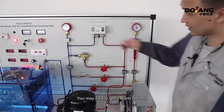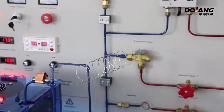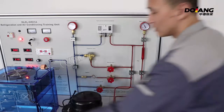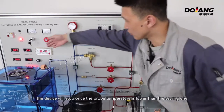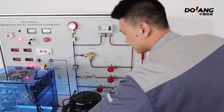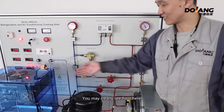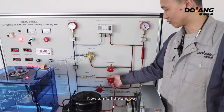You may clearly see it starts to freeze. If you need the device to run for a longer time, you may take out the probe. If you put it inside the evaporator, the device will stop once the probe temperature is lower than the setting one. You may clearly see frost here. Now turn off the second way.